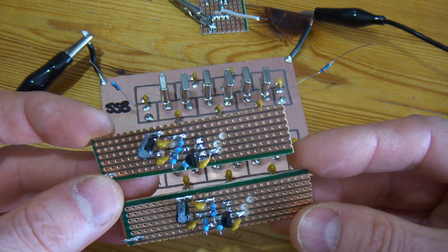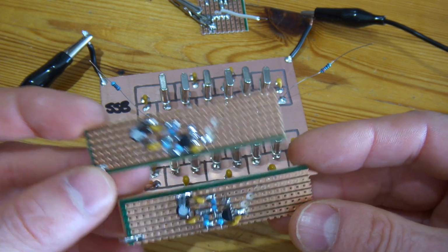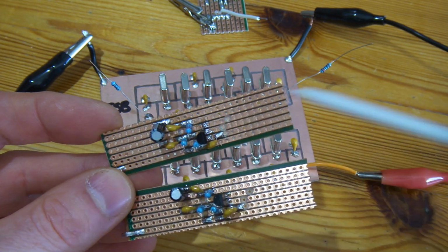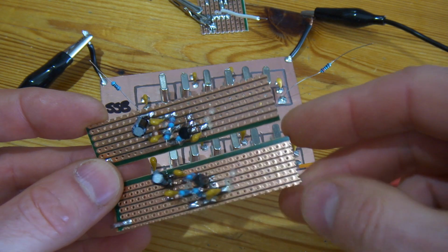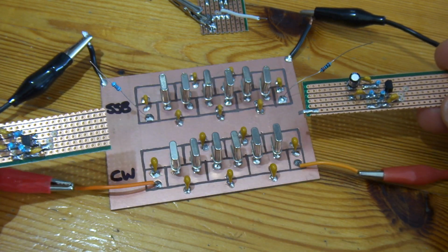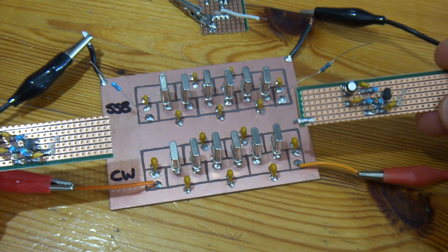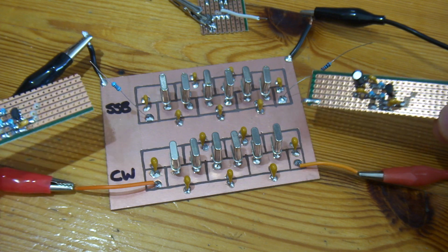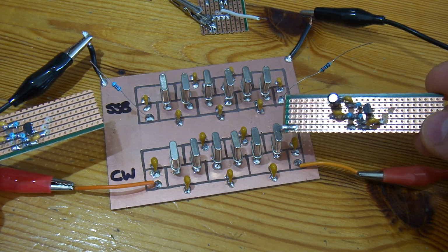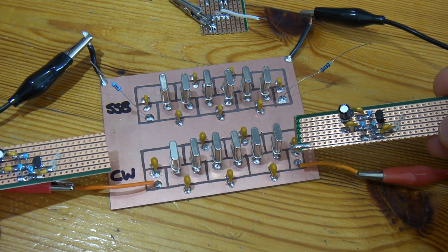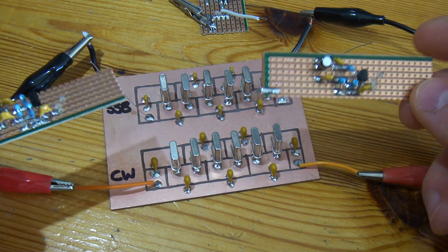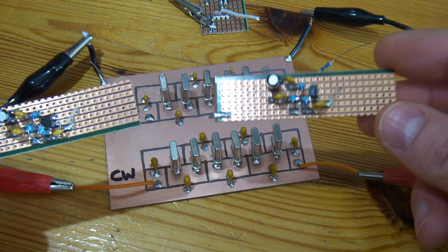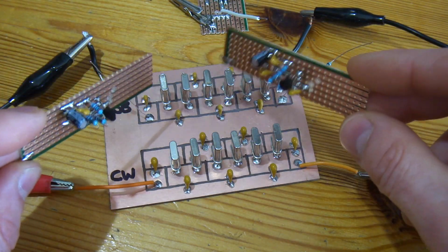And what I need to add to this now is the collector load. Being an RF amplifier, it's going to be a transformer, and so there'll be a transformer on the input and a transformer on the output, because these naturally sit on either side of the crystal filter. So the actual transformers themselves will have to reside on the crystal side, because, as I said before, the CW filter wants to see 50 ohms, and the SSB filter wants to see 170 ohms. So, like I say, I'll have the transformers on the crystal side.